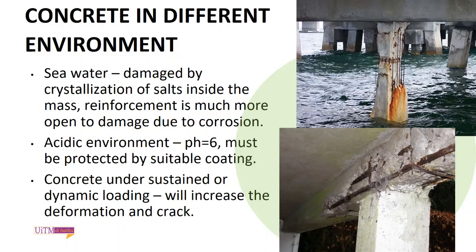And in an acidic environment, where the pH is 6, the concrete and the reinforcement must be protected by using a suitable coating. And when the concrete is under sustained or dynamic loading, it will increase the deformation and cracking.